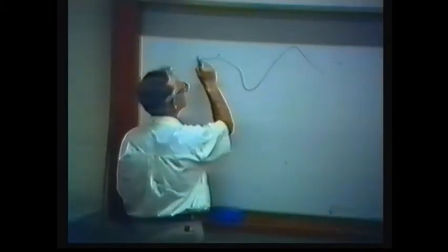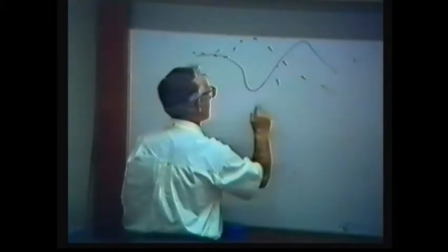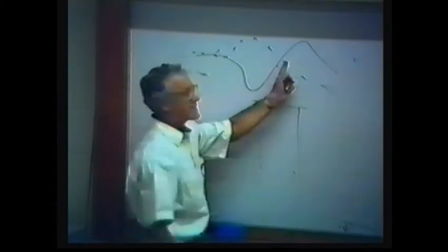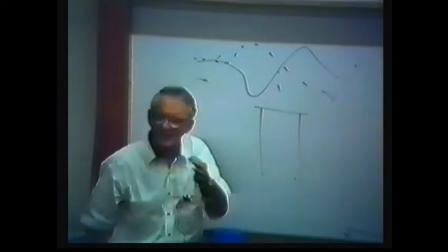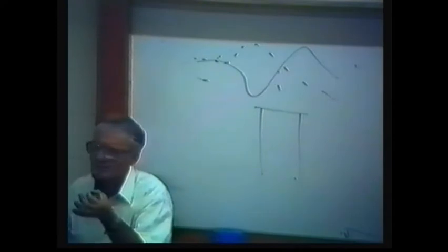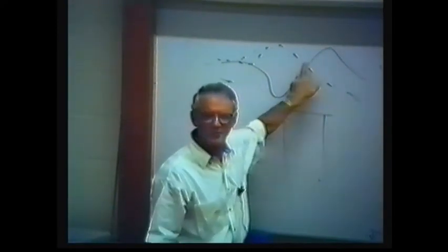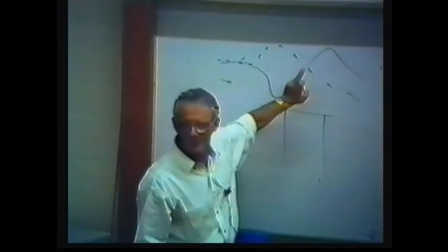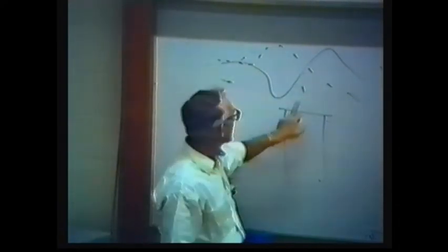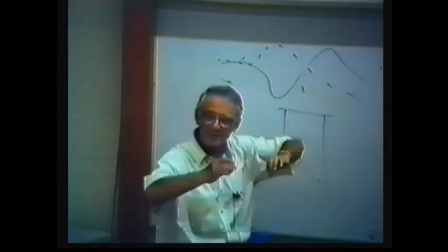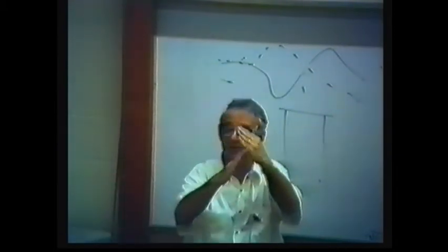But this crossover is an extremely remarkable feature. Usually above this dike you see what is called a conducting crossover. Because when you have a conducting dike, these two apparent resistivity curves intersect exactly above it. Since the environment is complicated, we are looking for good features. It's called combined profiling.